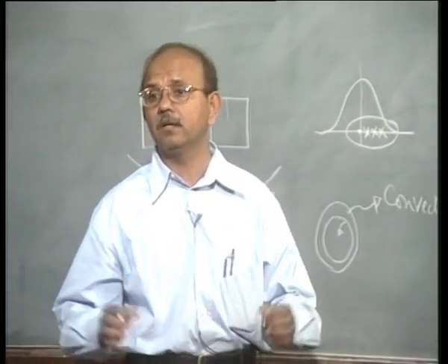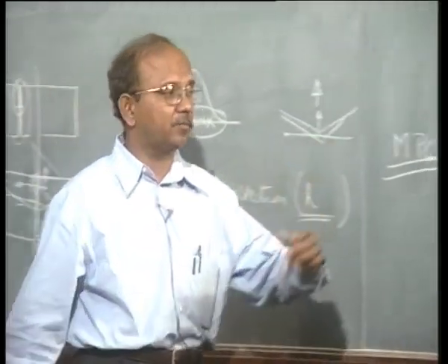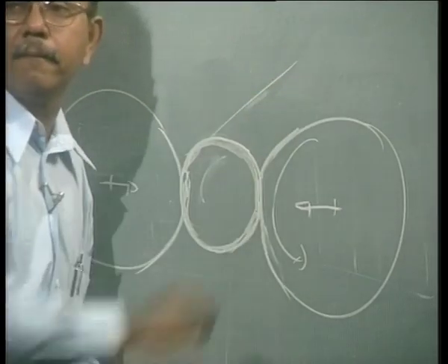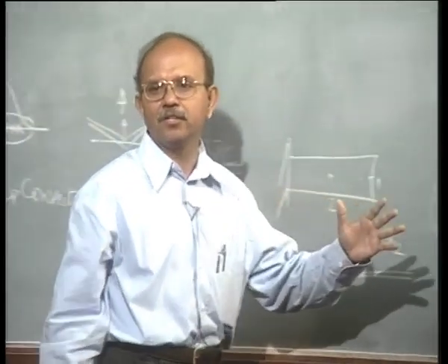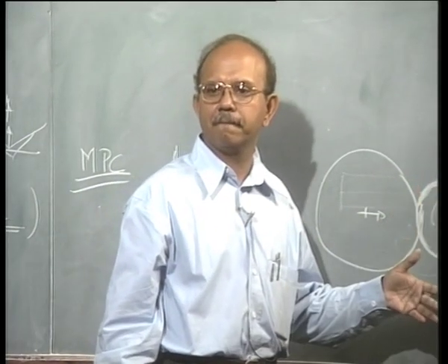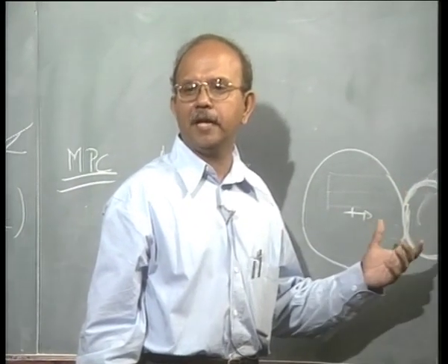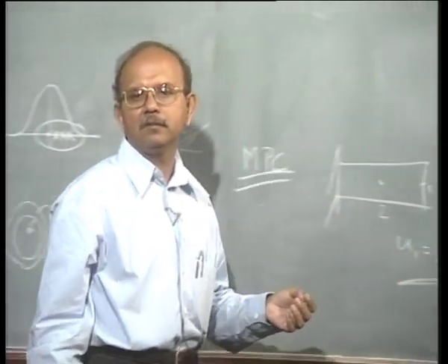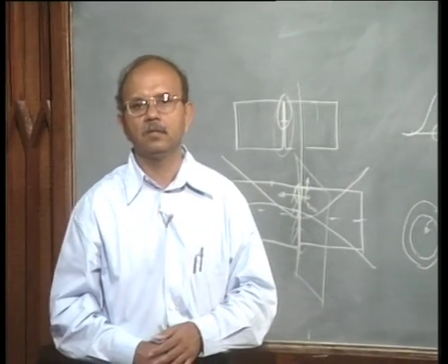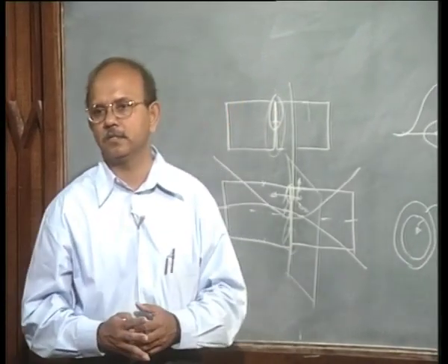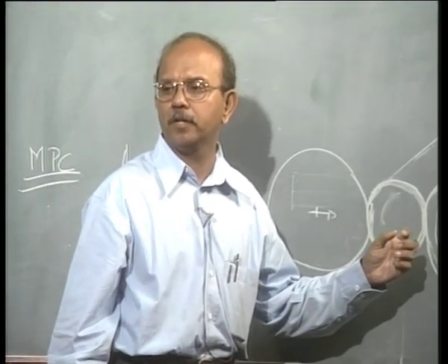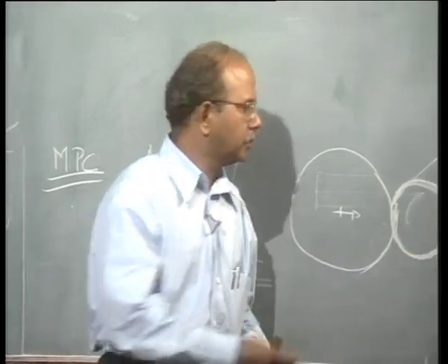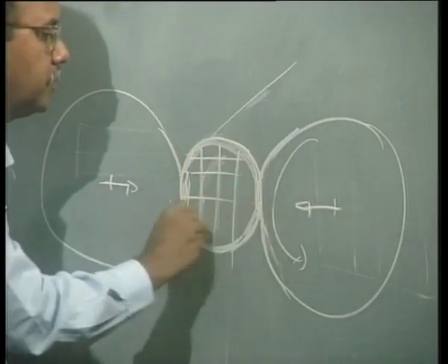It's a long cylinder. Do you use shell? Please note that it's a long cylinder, and the cylinder compresses. So plane, fantastic. You will use plane strain, so that you will do a two-dimensional analysis. If the diameter and the length of the cylinder are comparable, almost the same, then you may have to use a 3D analysis itself. Since it's a long cylinder, I can choose a plane strain element. So this body is now discretized by means of plane strain elements.